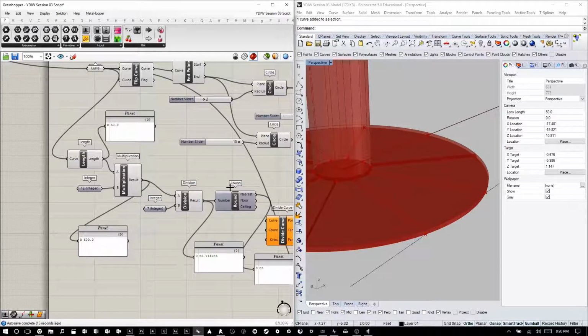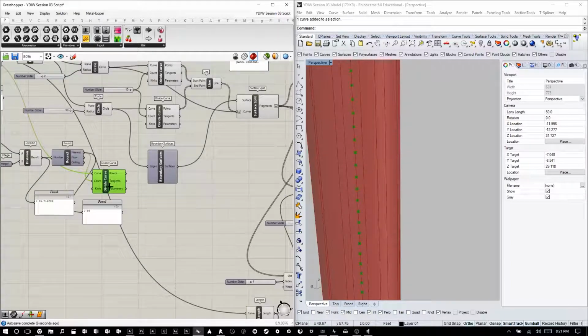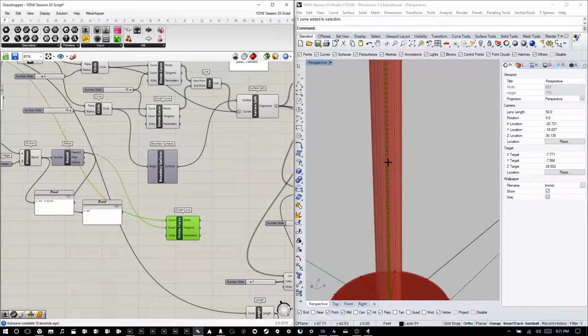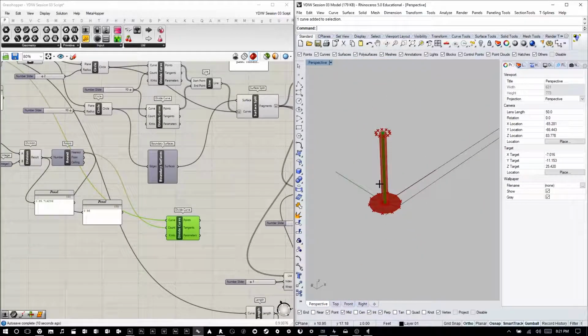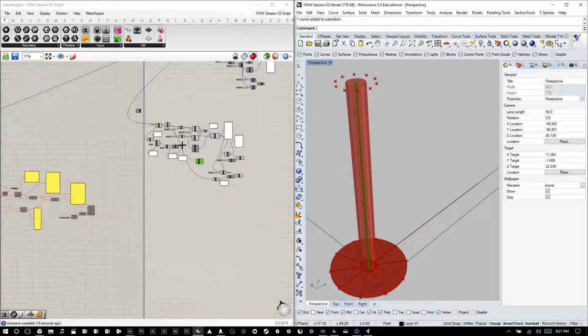And so the reason, again, I went through all this hullabaloo is to parametricize the height of this stair. So the original curve is my curve, and the number is my count. And so now that curve is divided 86 times, which will give me 86 steps going forward. Okay, so now here comes the hard part. This is the part that adds a little bit of confusion, but shouldn't, once we do it right.